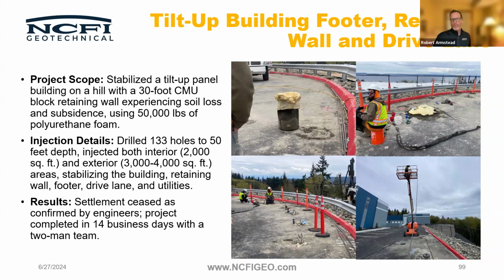Yeah, I mean, your soil report, you've got to do the investigation: your soil reports, your DCP tests, what you're estimating as your approximate voids, what you're estimating as your approximate soil density, what your soil type is. Do you have any subgrade structures that could potentially eat the material? Those are some of the things you've got to be really perceptive about, and try and do your preliminary investigations.